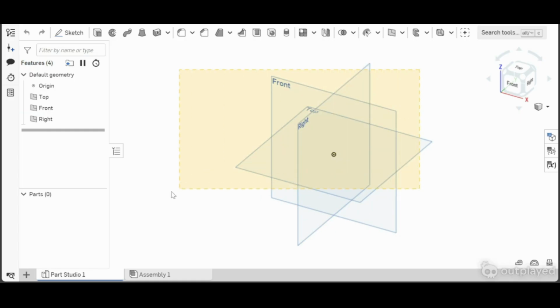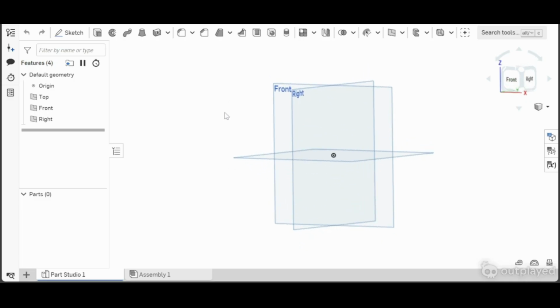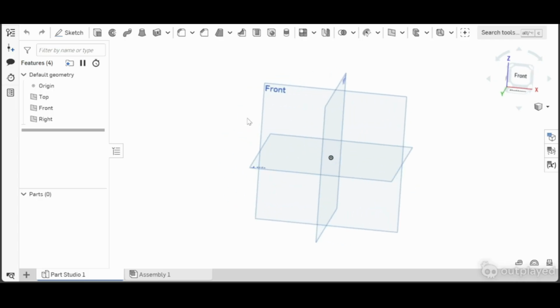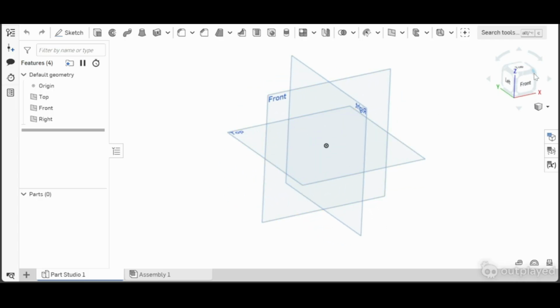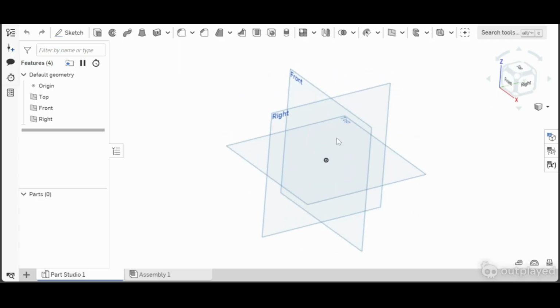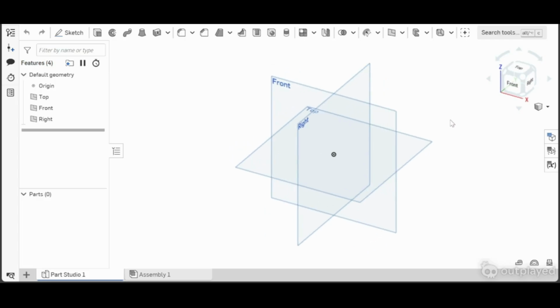If you left click and drag, you can select multiple things at the same time, but that's more for lines and stuff that we will use later. Right click will show an options menu based on what you click. And right click and dragging will tilt your camera view, so you can get a more exact angle of what you want to look at in the view cube.